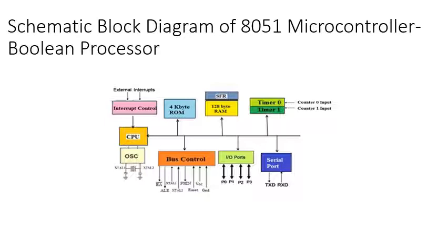The 8051 memory architecture includes 128 bytes of data memory that are accessible directly by its instructions. A 32-byte segment of this 128-byte memory block is bit addressable by a subset of 8051 instructions, namely the bit instructions. For this reason, the 8051 microcontroller is known as a Boolean processor and is used to deal with binary input and output conditions very effectively.